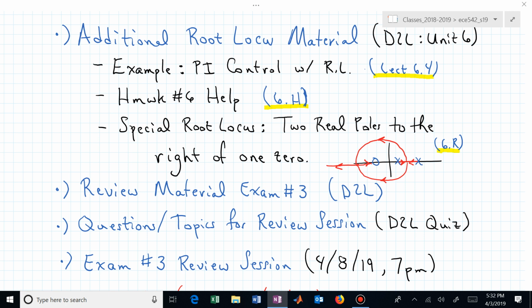It actually is related to their distance from the 0, and it's a geometric mean. We'll talk about this later, or that's actually in the special root locus lecture, I hope. But the circle is formed by putting the center of the circle at the 0. Once you've found the breakaway point between the 2 poles, that's established your radius, and you can use that radius to draw the root locus branches that are off of the real axis.